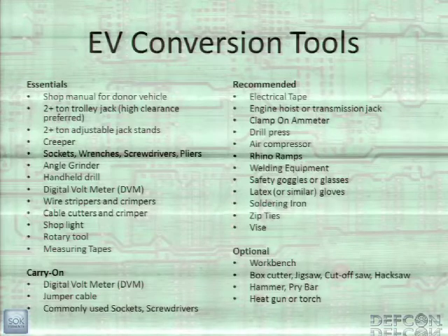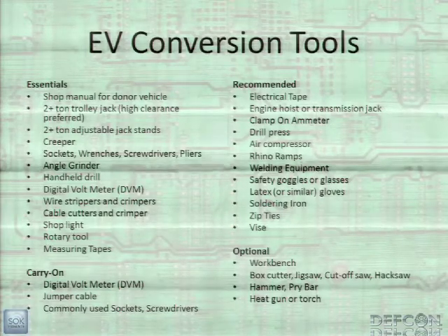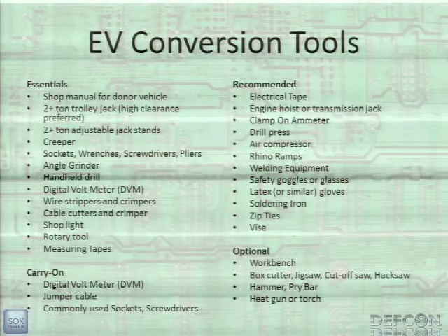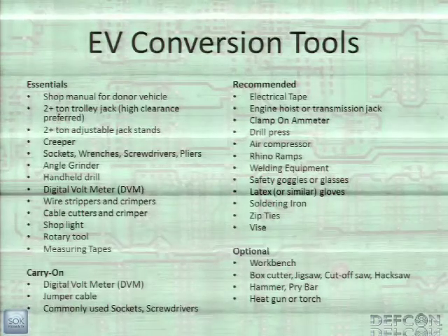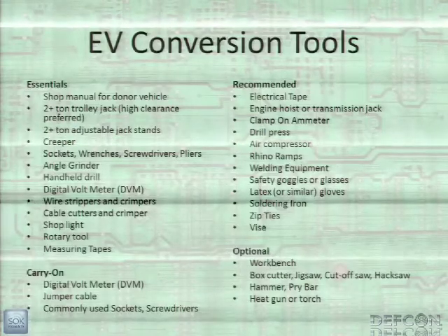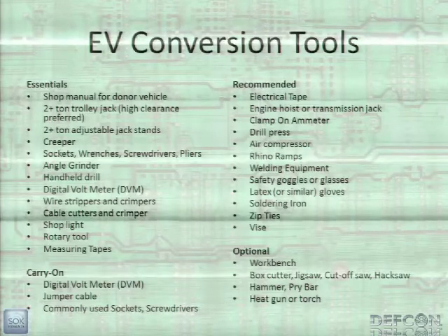Also, all your tools, you should put some insulation around the handles. You don't want to be using a tool and have it smack against a battery and short things out, because then you've created a welder that you're holding. So I, of course, didn't bother to do that until I had my first high voltage event, and then I went and did it.